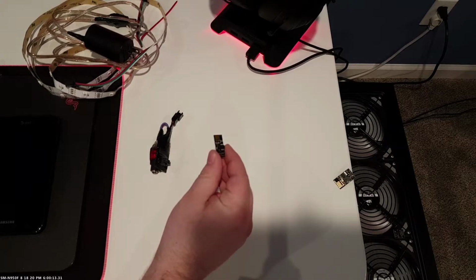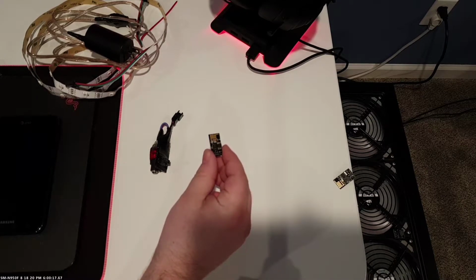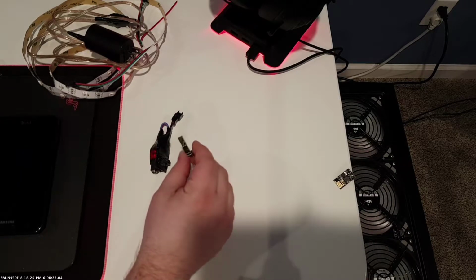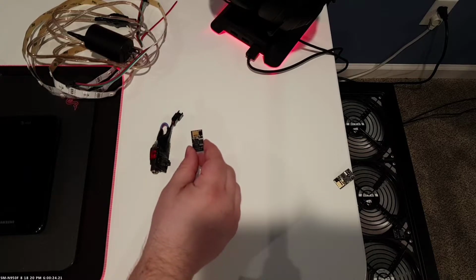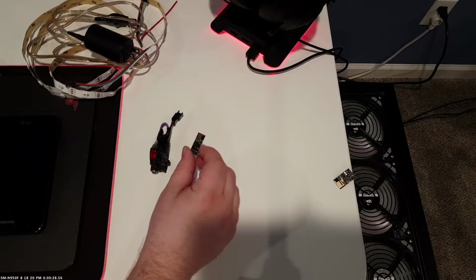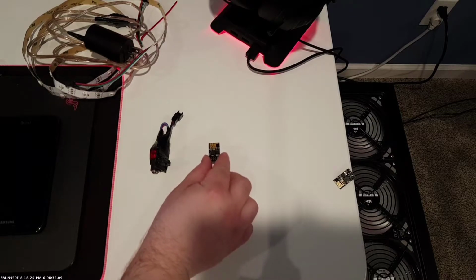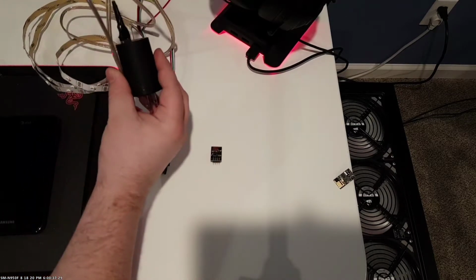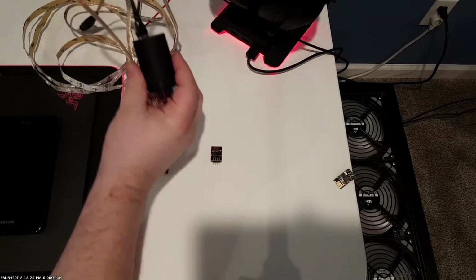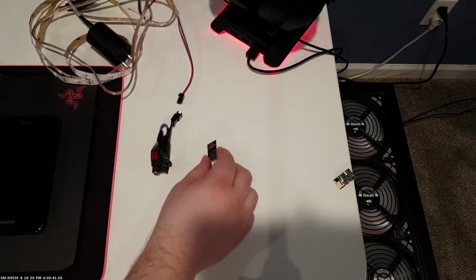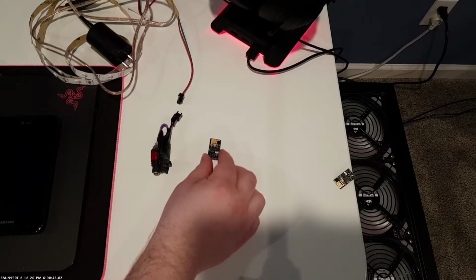It's an ESP8266, which this particular board is called an ESP01. It's the cheapest ESP8266 board out there, and it has a few drawbacks. The main one is that it doesn't provide a 3.3 volt regulator. So if you want to power it off of a 5 volt power supply, which is what I'm going to use, which is this tablet charger, then you have to provide your own regulator to get 3.3 volts for it.